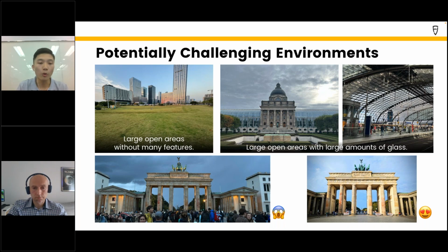Also, large open spaces without any buildings or objects around the scanner and your project area are hard to scan. So make sure you clean the area during the scanning initialization and also point the LiDAR towards a feature-rich environment. And lastly, don't scan areas with moving people or vehicles, like crossroads or plazas, as in the bottom left picture. You'd like to have a better scanning result like the bottom right photo.